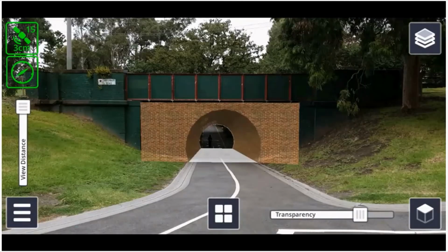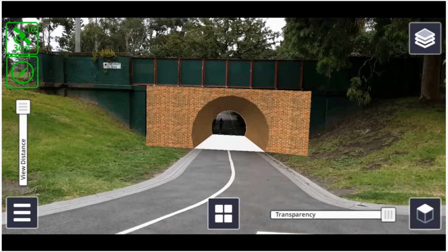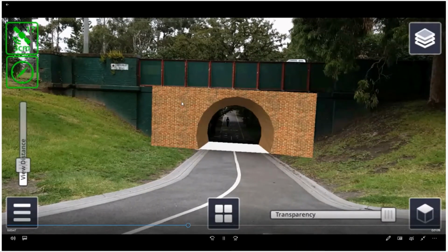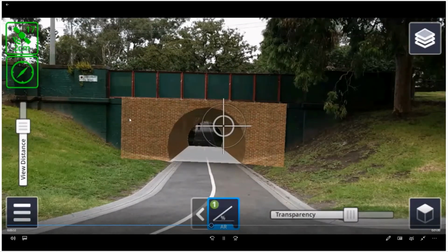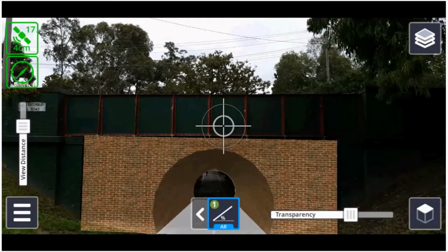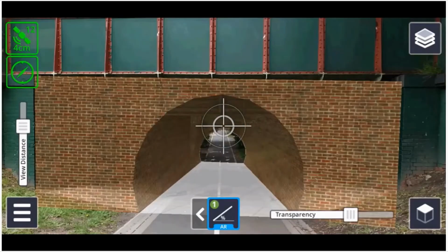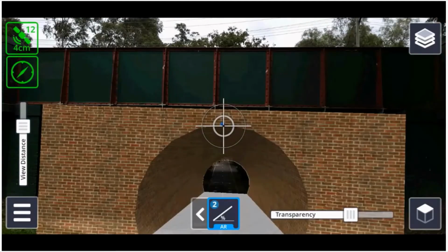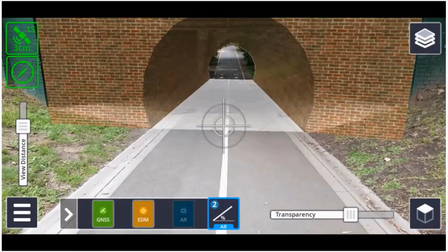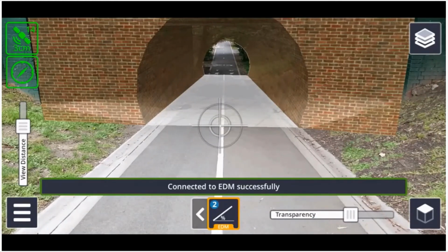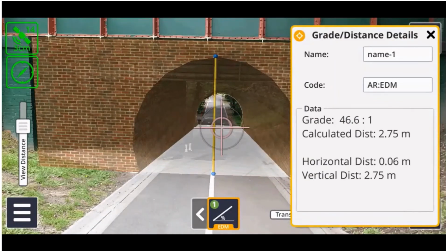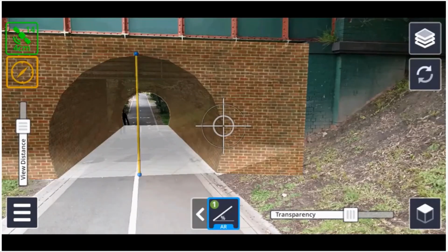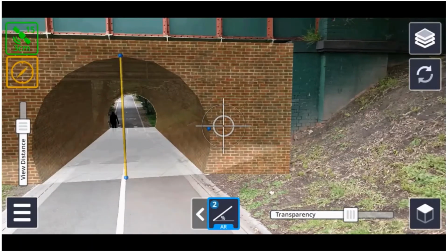But in this case, you can see here a little tunnel design that I've put underneath this bridge abutment, and we can fade that in and out. And it allows us to get that really immersive take on this. And this is still using the same things that we've used so far. The initial survey was done with Trimble Access. It was positioned with an R10 rover, so that when we did our design, placed the design, creating a quick calibration file from Business Center and loading that through the Sight Vision workflow, then it drops straight into where it